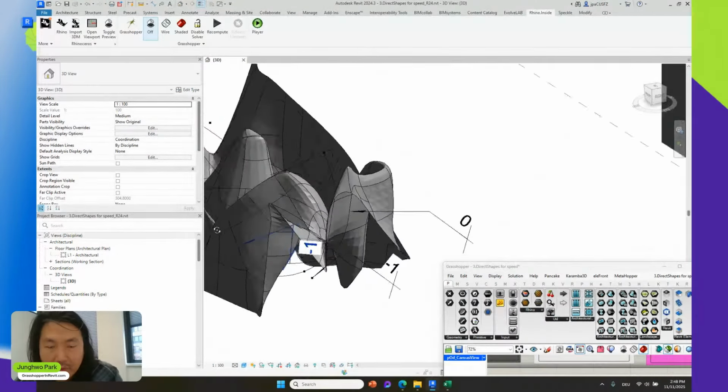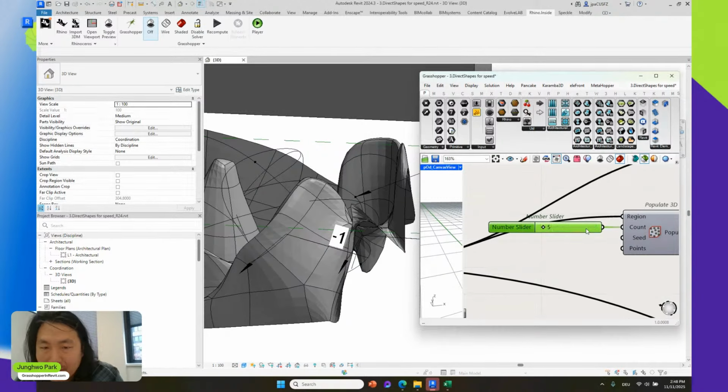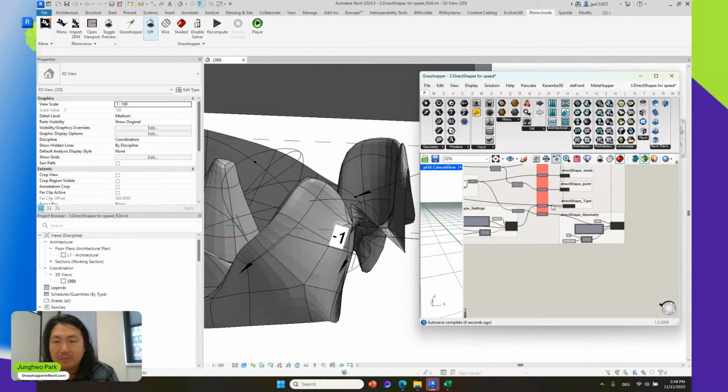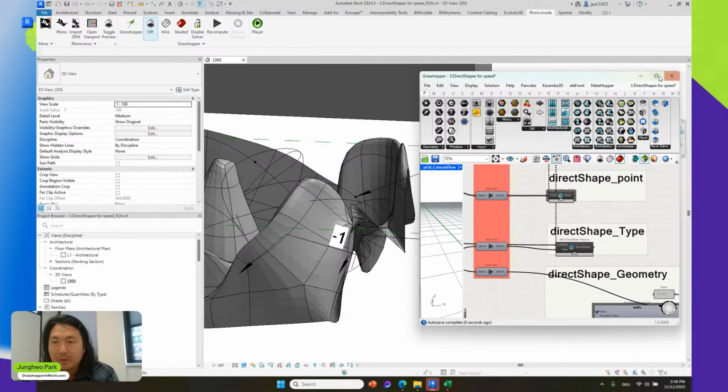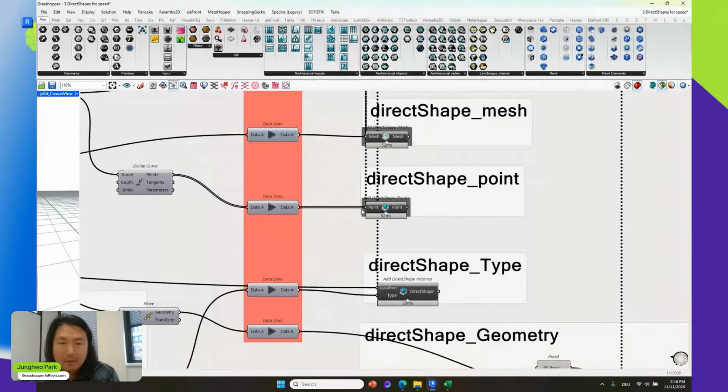But if you, of course, bring less points, then basically Revit will lose those elements. And then if they cannot track anymore that Revit ID, then those annotations also will be deleted. So you need to think about also at the same time Revit's behavior, but this will give you quite a good workflow to reflect design changes.